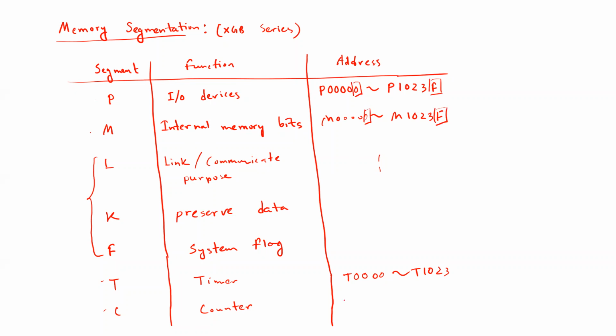However, in case of timer and counter, that extra digit is not present. So normally, the number of addresses may differ from model to model of different PLCs manufactured by LS brand in their XGB series. But in general, this can be indication of the different memory locations available to the user.